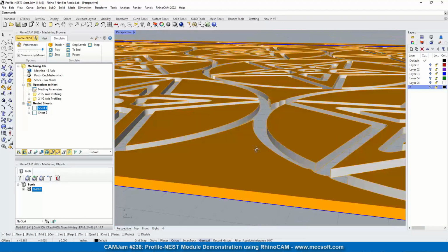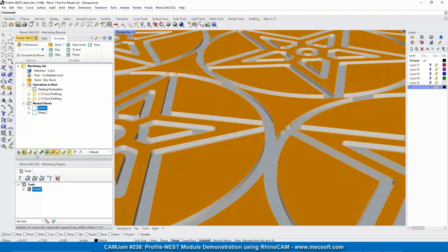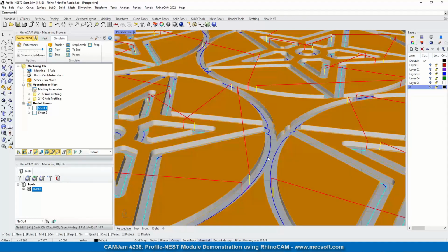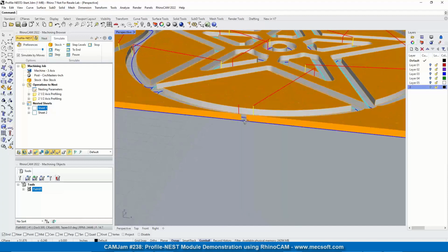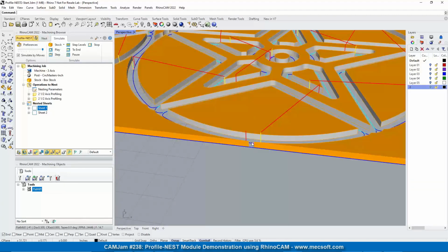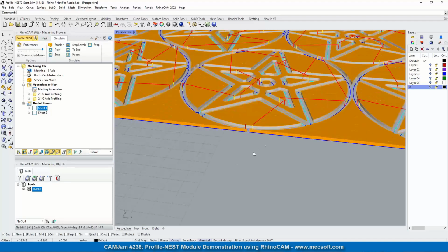And if you look at the toolpaths, you'll see that the distance that we set is 1/4 inch from toolpath to toolpath. So if you wanted, you can tighten that up to 0 and it would be right on it. But typically you wouldn't want to do that. A little bit of spacing between the two. You can even go tighter than 1/4 inch. And we set the outside perimeter 1/4 inch as well. So you can tighten that up if you want to also.